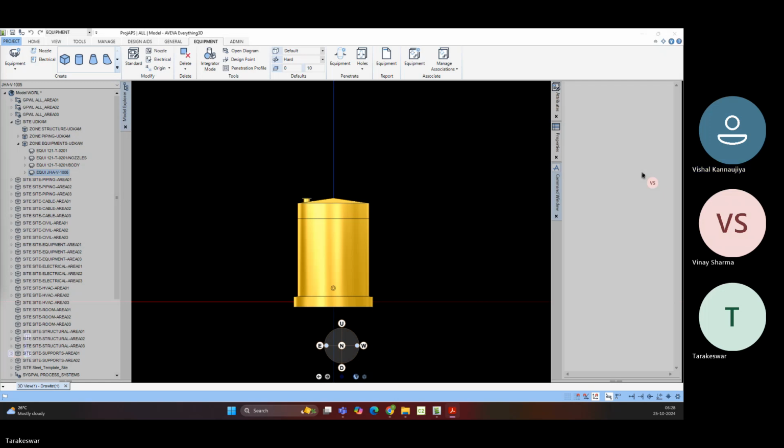No, sir. Okay. Another thing: piping connection is done through two points, meaning two things. One is connect position and another is split position. Connect position is like this: for example, you have two equipments, one is a tank and one is a pump. From this tank to the pump nozzle, a connection is given. That is called connect position.